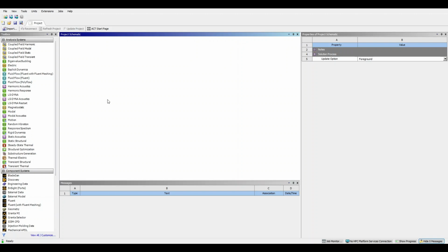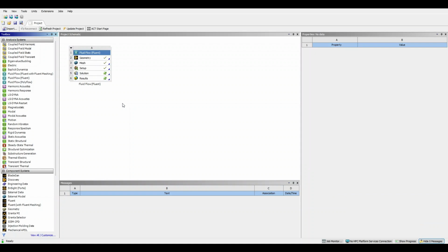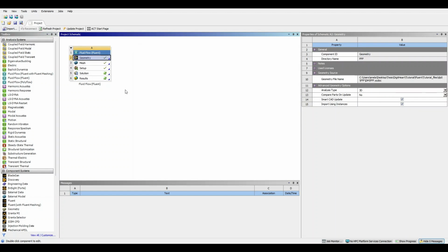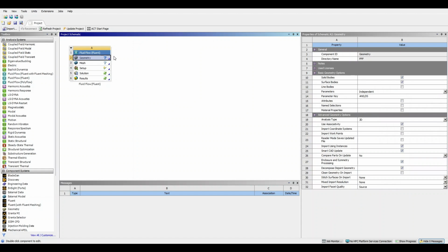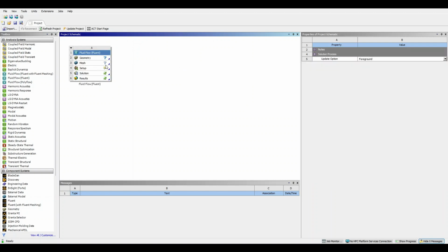So, as I said, we start from the Workbench. It is important that we load our simulations here so that we don't have any problems with negative volumes in the moving mesh and so on. So we load this Workbench, and then you can save it with your name or your geometry or whatever. Then the first step would be to reset the geometry so you can upload your own geometry. Of course, if you're working with our own geometry, then you can just skip to the setup.